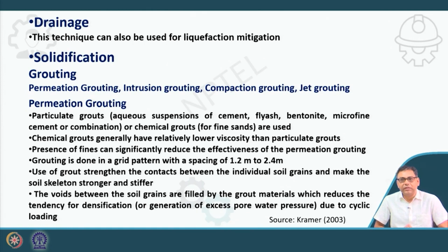Okay, so when you use this grout, it basically strengthens the contacts between soil particles, so that the soil skeleton becomes stronger and stiffer. The voids between the soil grains are filled by the grout material, which reduces the tendency for densification or generation of excess water pressure due to cyclic loading.